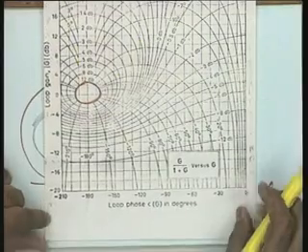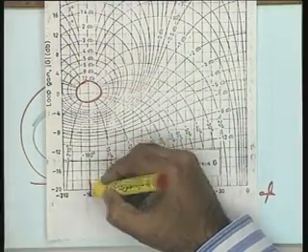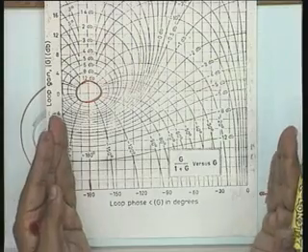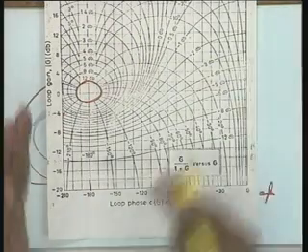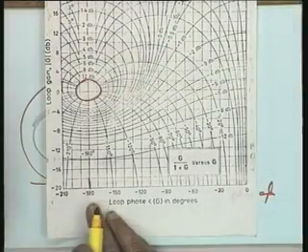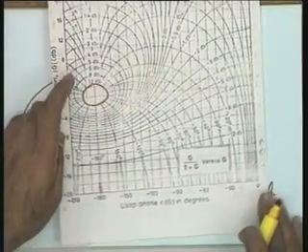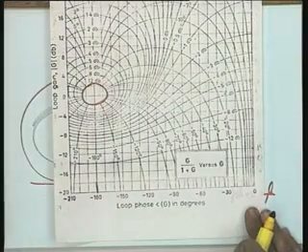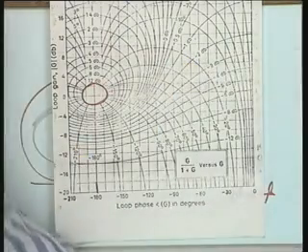You will note one point here, the complete axis is around minus 180 degrees, because normally the working area is this. So, I have taken a Xerox of a page where the Nichols chart is with respect to minus 180 degrees, with more working area available in this region. But otherwise your Nichols chart is available for 0 to 360 degrees. There is absolutely no difficulty here, because these lines are symmetrical.